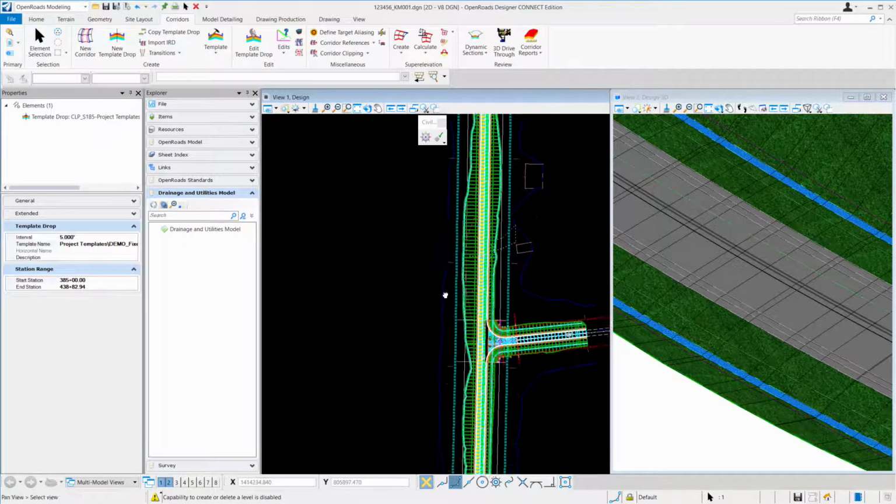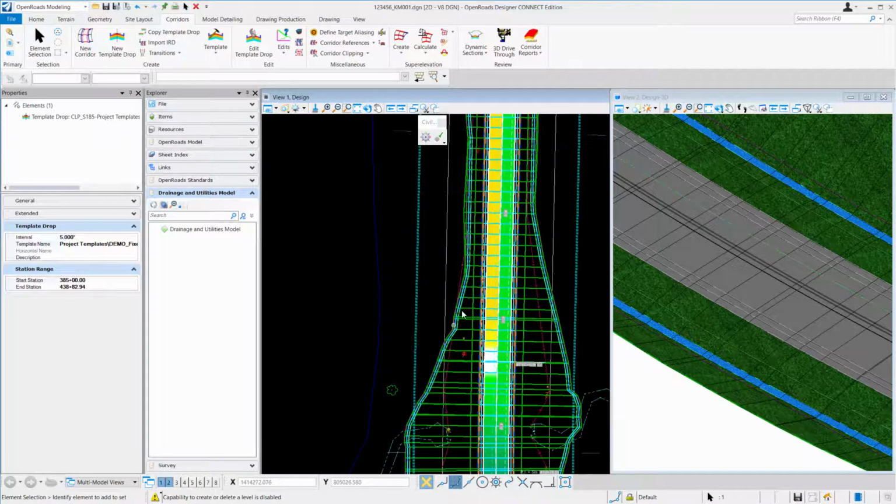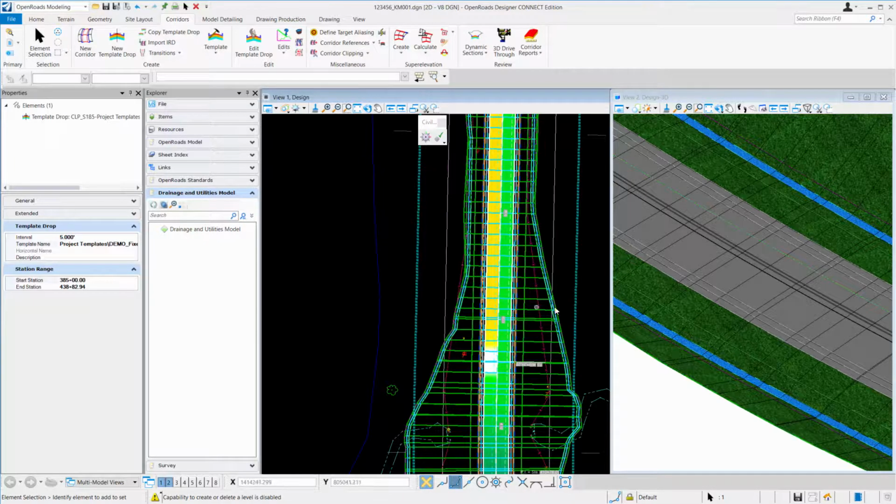This is just an example, so obviously apply it as needed. Now maybe I want to smooth out this profile here. This gives me a good spot, but right now I can't really add any point controls or constraints to this, as it'll mess up that fixed ditch template. As I mentioned in the last video, the way it's set up is not really conducive to applying a bunch of edits to it. So it's a starting point. Let's go get that profile projected onto our centerline alignment, and then we'll come back and switch the template back to the regular one, and then use that projected profile to control our ditch. Okay, so I'm going to switch over to my other file now.